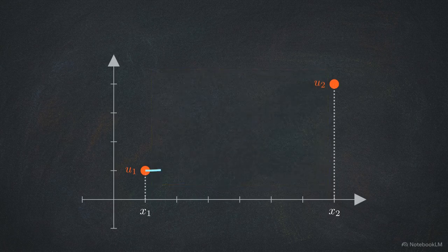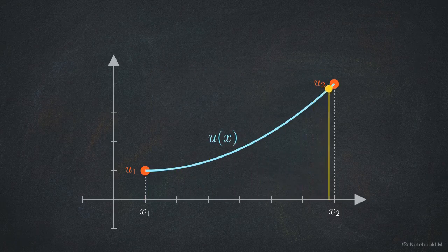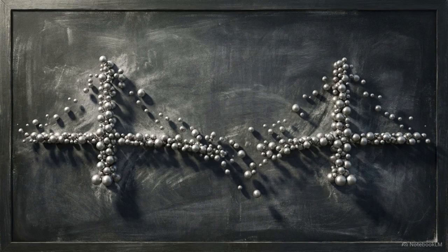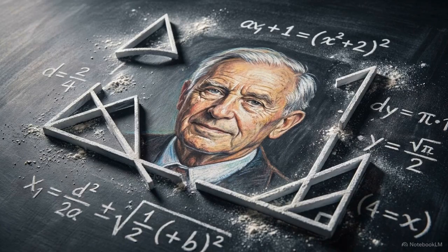To cross this void, we use interpolation functions, mathematical approximations designed to predict the field based on limited nodal data. Without a precisely derived interpolation function, your discrete nodal data remains a collection of disconnected dots, entirely useless for simulating real-world physics. To build this mathematical bridge correctly, we apply a specific weighted residual approach known as the Galerkin method.